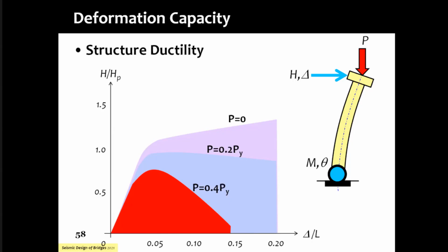So the key factor that you're learning now on this picture is that if you put very heavy loads on a column, then you will get very brittle behavior, and lighter loads will give you ductile behavior. And then you might say, what is the meaning of heavy load? Load is always fixed. Yes.